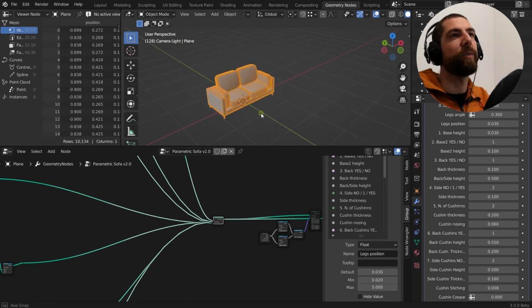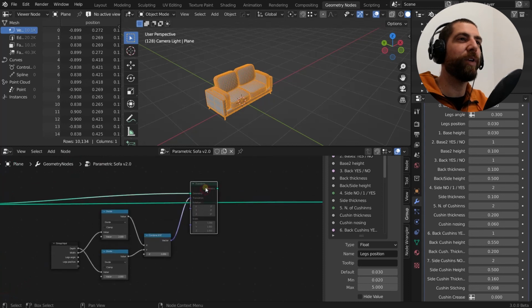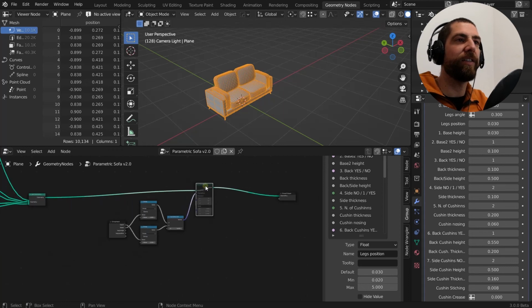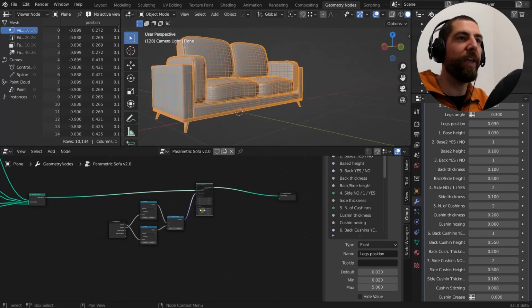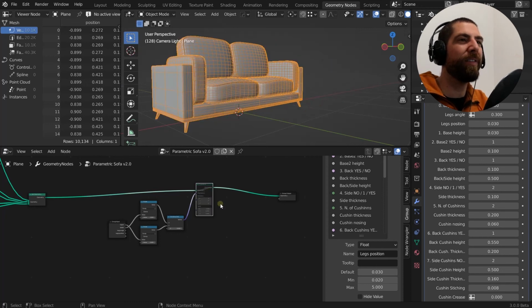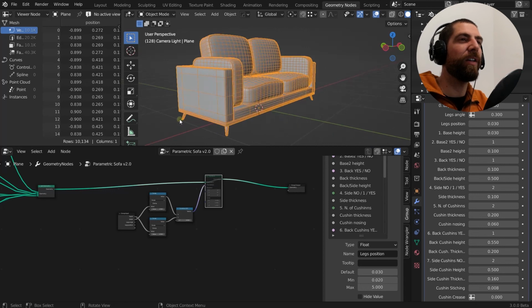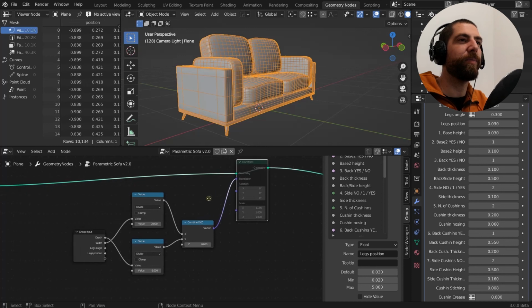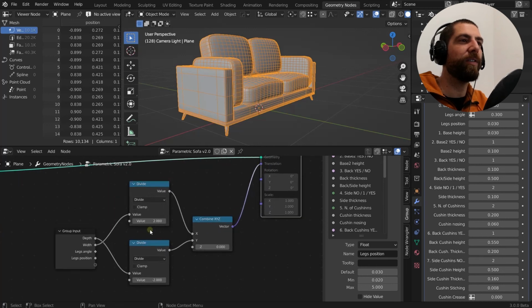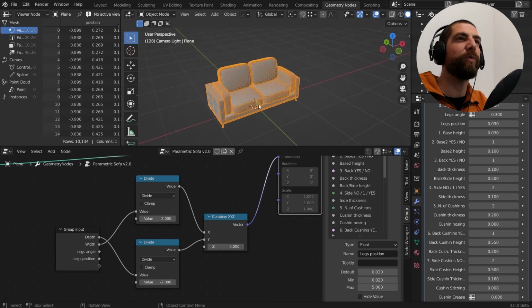And the last thing I did, I just passed it through the transform node and I translated it. Now it's muted with the M. See, M unmuted, M muted. The last thing I did is placed everything with its origin point here, and it's simple. It's just translation on the XY axis, depth divided by 2 and width divided by 2, and it gets moved here.